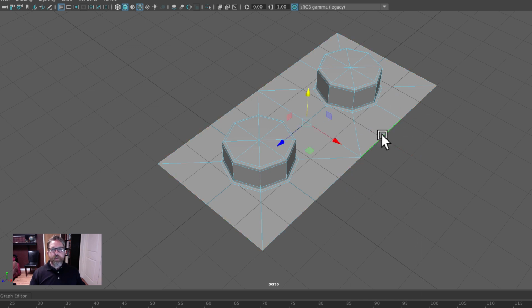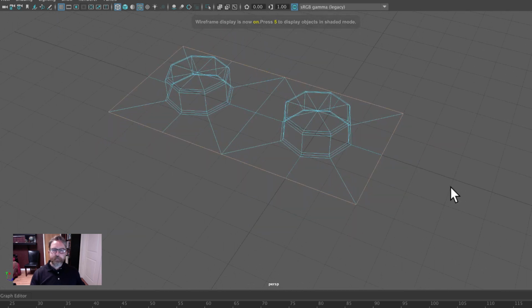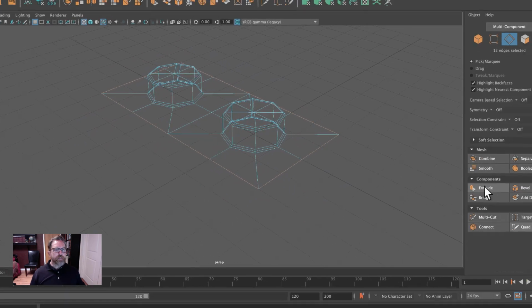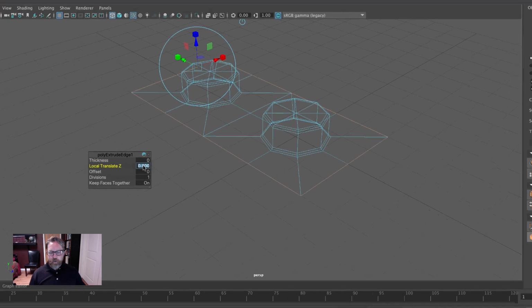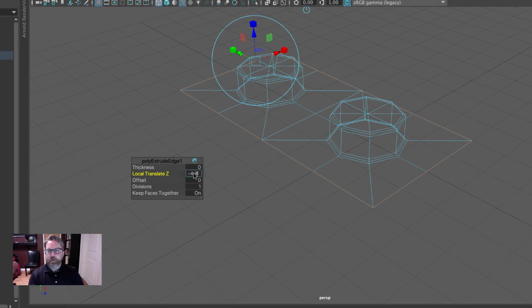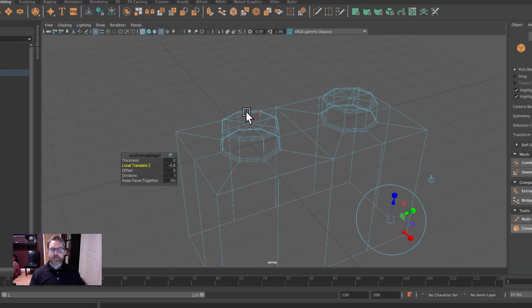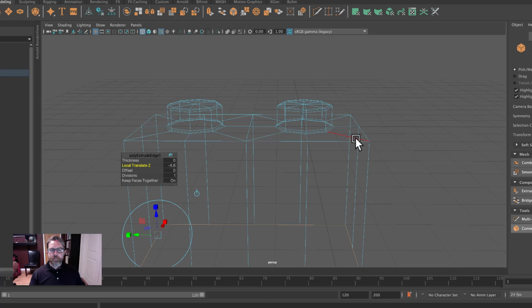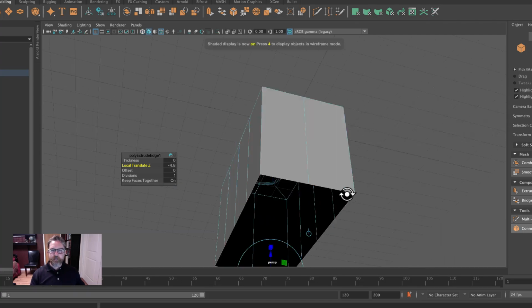So we'll double click the outer edge, hit the 4 key just so that you can see that. And we'll come and we'll extrude. We're going to extrude this edge. And you'll recall that we went negative 4.8 units based on the size of our peg. This would be the height of our brick. You can hit the 5 key and see that.